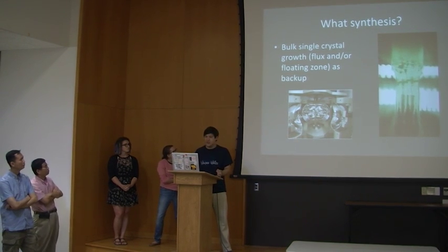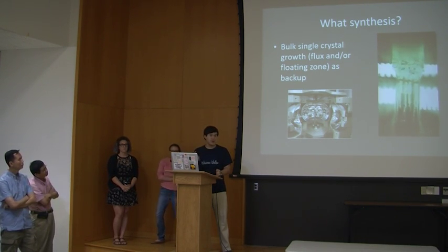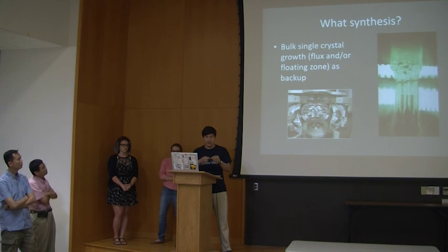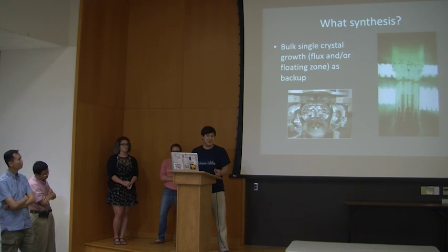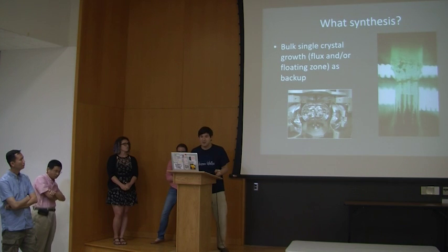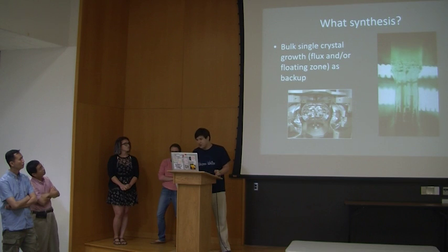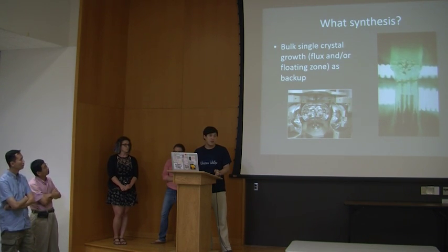And so this focuses all of the heat onto a single point on a rod that is then lowered slowly, and that makes the sample at that point melt. And as it comes out of that point, it immediately crystallizes, it immediately crashes out, and so you get a very long single crystalline rod. And so we could definitely do it for this material. In fact, I think it was done for this material, using niobium oxide as the solvent, which melts at 1,500, which to us is a lot, to the floating zone is nothing. And so a single crystal, if cleaved correctly, could also be used for some of the characterization techniques we're going to discuss later, but MBE thin films are ideal for that.